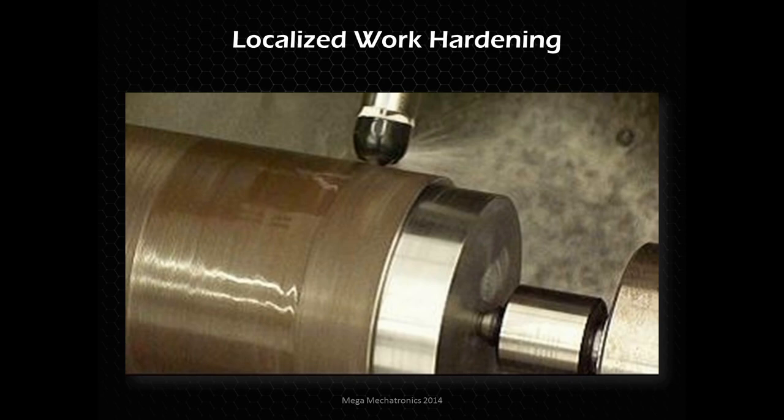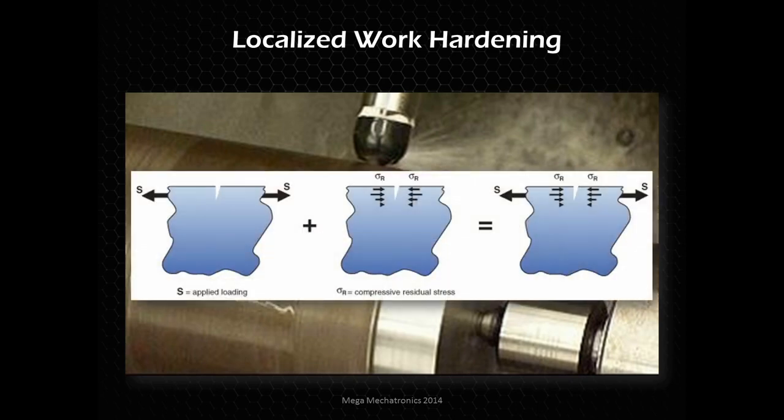And then touching on compressive stresses, why those are important. If we look at, on the very left, a material, let's say it has a little crack in there. But if there are compressive stresses, everything's trying to push things together. Those compressive stresses are pushing that crack back together. So when you apply that load to split that crack open, there's actually compressive stresses countering that. And that's what gives it fatigue strength and things like that when you shot peen a part or roller burnish it.